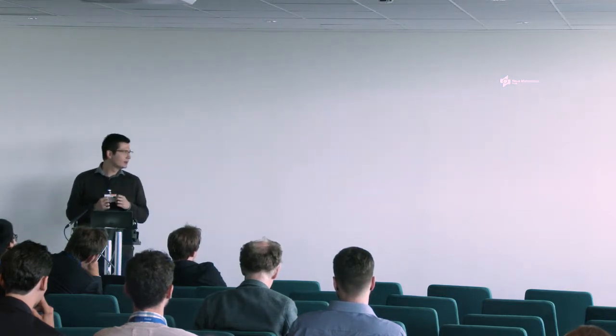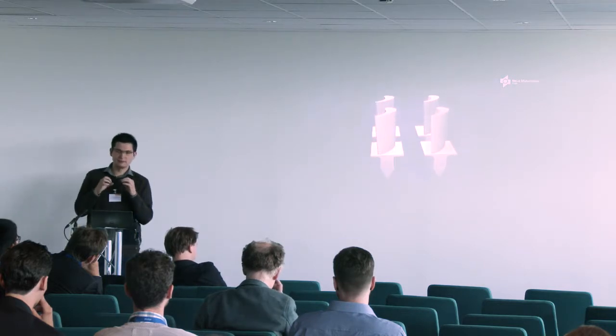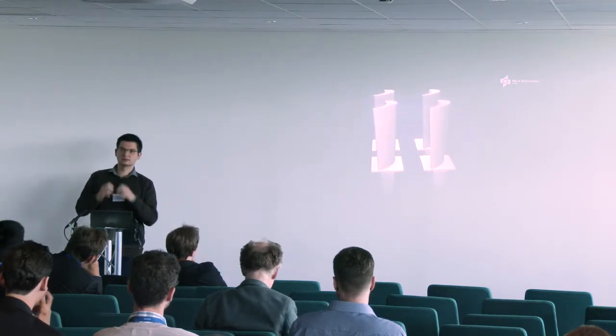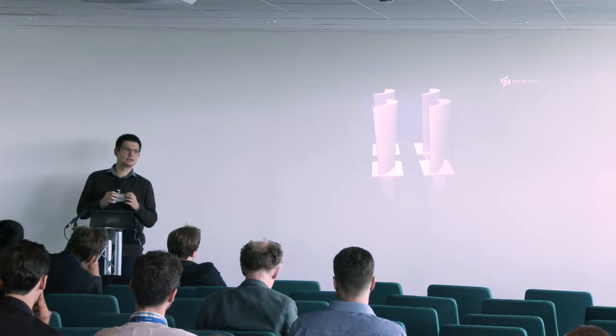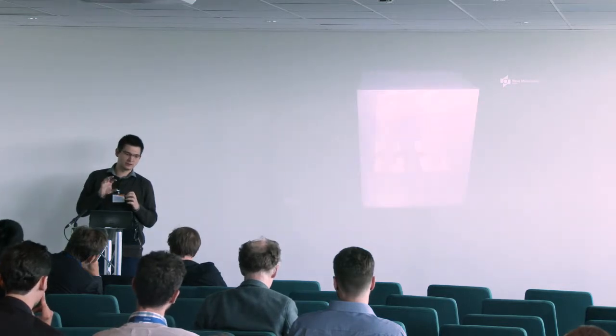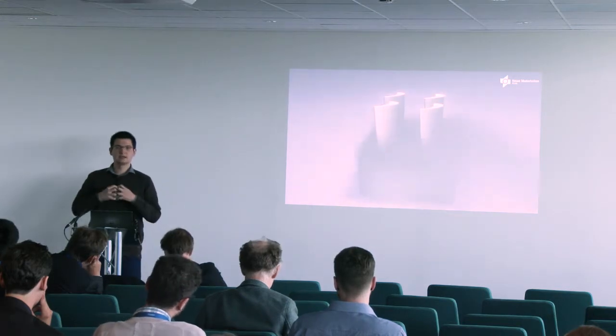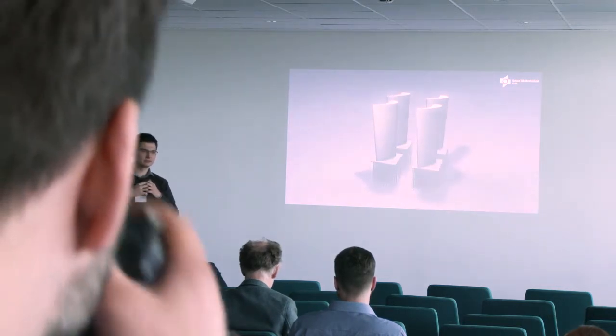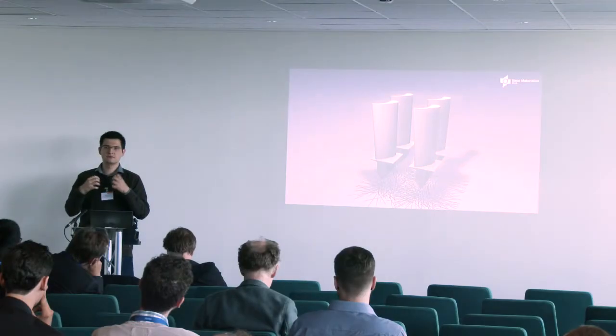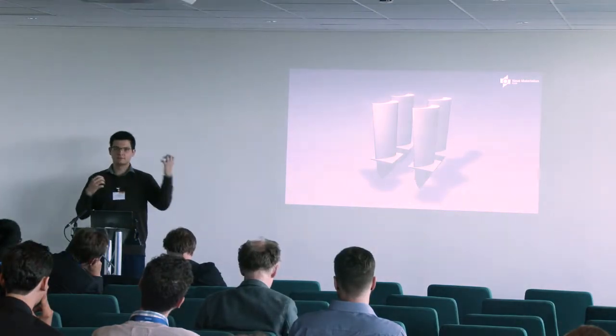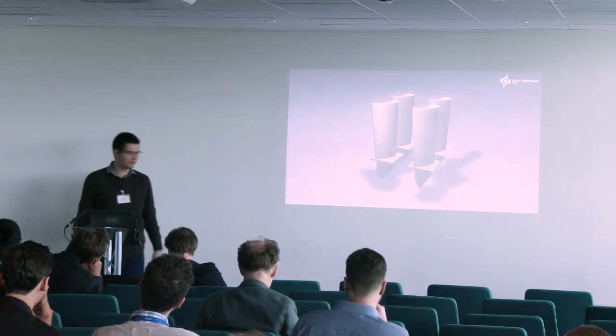So we are working at high temperatures that allow solid state sintering, so solid state diffusion. With this powder bed, we have it mechanically stable, so that increases not only the electrical conductivity of the powder bed, but also has a force between the powder particles. So even if they get charged up, they stick to the powder bed.